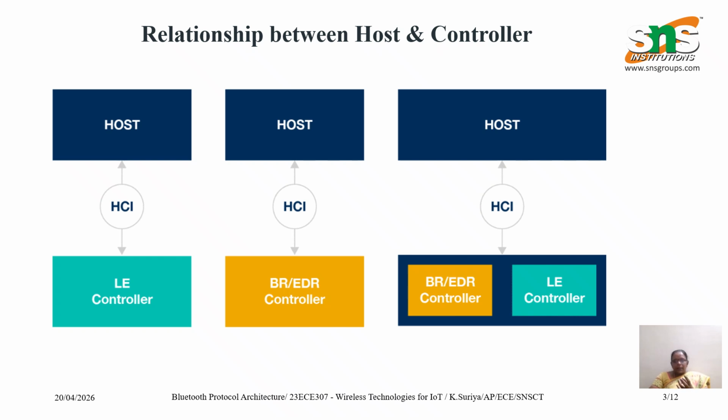A controller can support BR/EDR, or low energy, or a combination of both, while the host is the same for both technologies. This is because the fundamental differences are found in the lower level protocols of the stack, physical and media access protocols, each implementing its own set of commands and packets, while the higher layer protocols implemented in the host are not exclusive to BR/EDR or LE and are common to both.